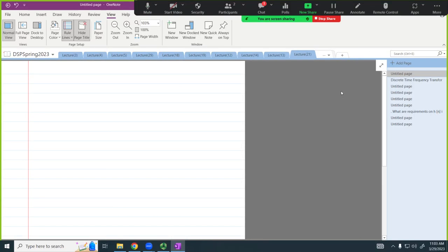So in the previous class, we looked at the design of different filters, high pass, band stop, and we said there are two methods of designing these filters. We either can design the intended filter in the continuous time domain, and then we use a bilinear transformation to transform it to the digital domain. We've done an example with a band stop filter, and we did one with a high pass filter. So with these, we can do any of the other filters.